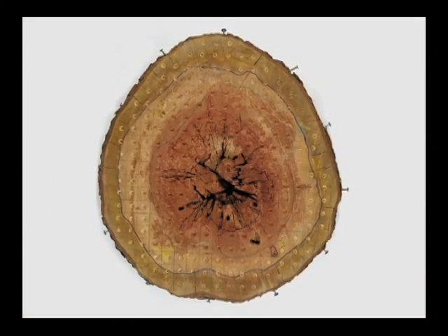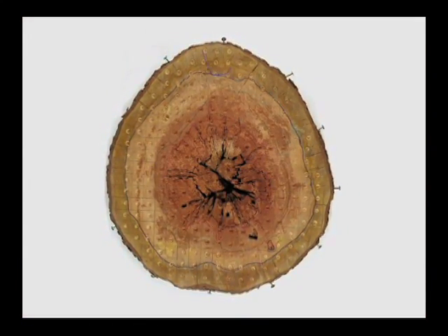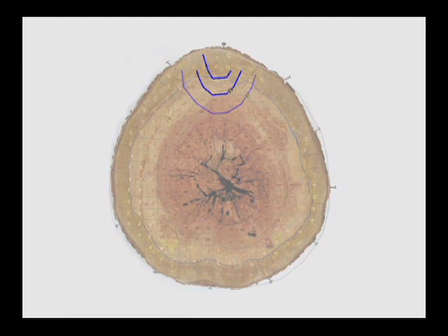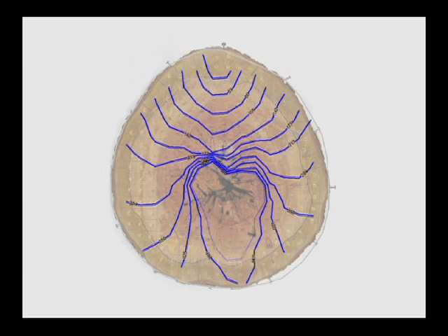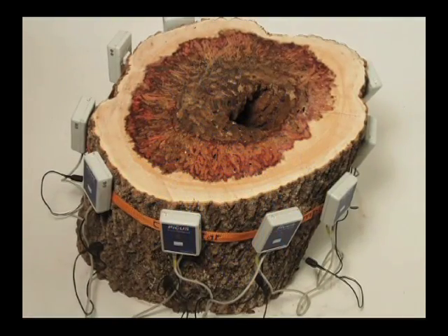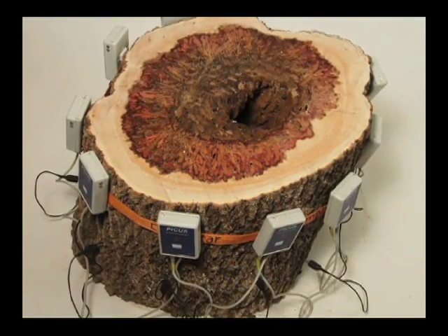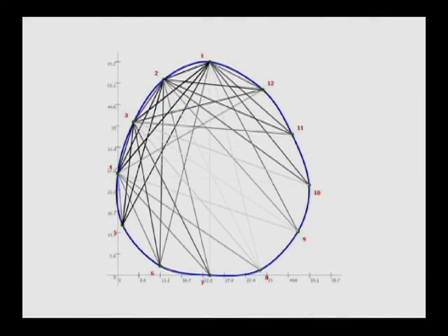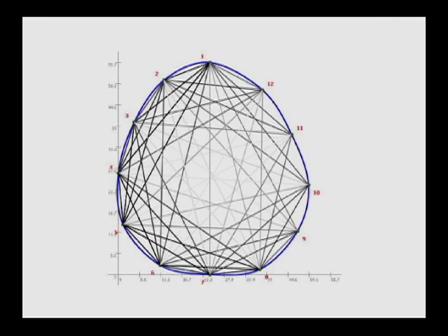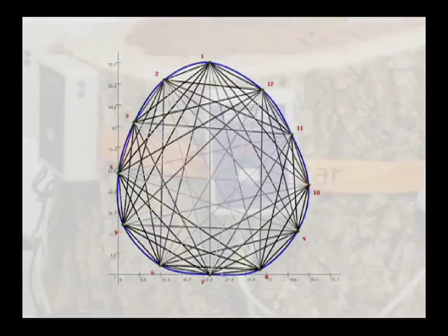Stress wave propagation in wood is related to the physical properties of the wood. Stress waves travel faster in defect-free wood. Areas of cracks, cavities, or decay-induced low density will require longer times for the stress wave to arrive at the opposite timing sensor. With multiple measurements from an array of timing sensors, computer software can create a projection or two-dimensional map of the acoustic characteristics of the sampled area.